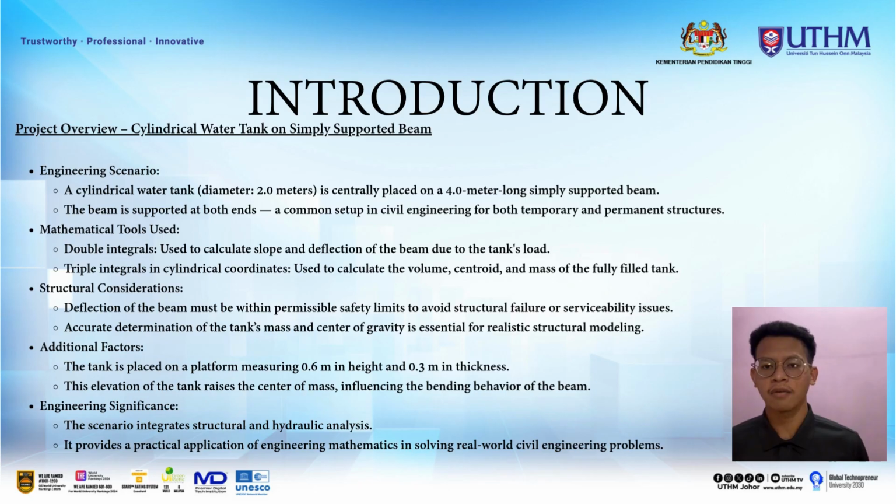These calculations are vital for ensuring that the deflection remains within safe limit and that the tank's mass and center of gravity are accurately represented in the structural model. Additionally, the tank rests on a raised platform measuring 0.6 meters in height and 0.3 meters in thickness, which increases the system center of mass and affects the bending behavior of the beam. This project combines structural and hydraulic consideration and demonstrates the practical use of engineering mathematics in addressing real-world civil engineering